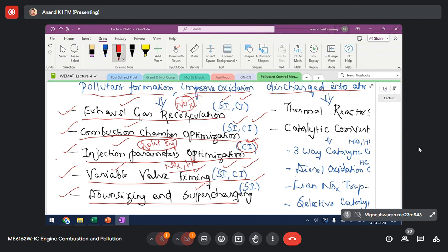It is like internal EGR. Residual gas is also called internal EGR. It's nothing but products of combustion. Retaining more EGR inside the cylinder is going to influence NOx formation. As we know, the primary effects are a drop in temperature and a drop in oxygen concentration in the cylinder if you retain more exhaust in the engine cylinder.